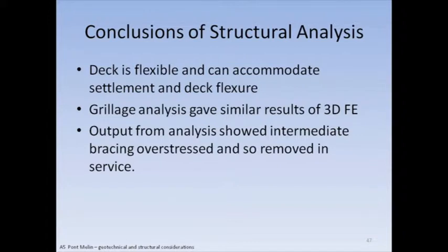Being involved in the Category 3 check, most of the background work had obviously been done beforehand, and working with the designers, the main thing that was found was that the bracings that were needed for the erection of the structure, the tolerance ties between the beams and the bracing for the brace pairs to lift in, were actually the elements that were overstressed when the bridge was in service.